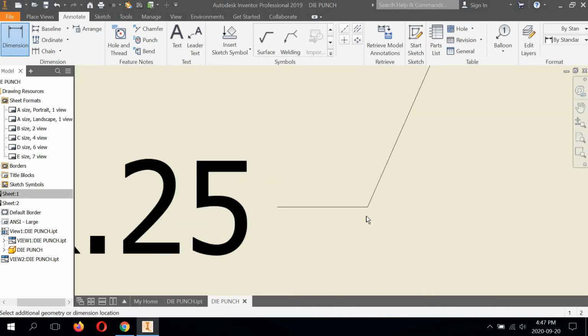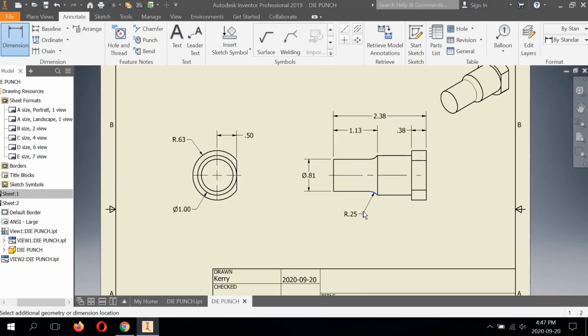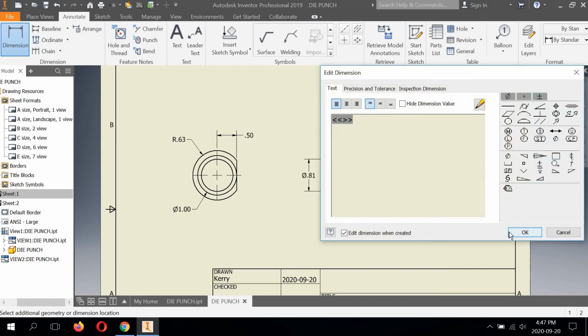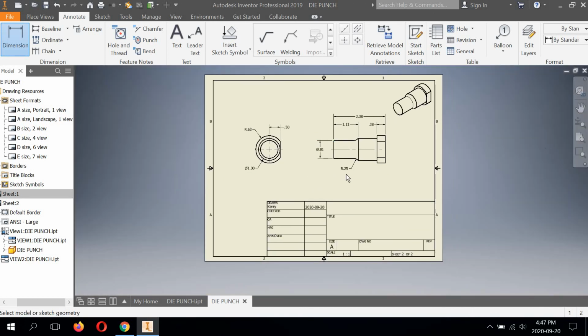Radius dimensions don't really go broken like the linear dimensions. So these ones you kind of have to eyeball to look as best you can, but I would try to copy the kind of distance we've done so far. Not too close, not too far, somewhere around there, and then hit OK. So there you have it. So there we have all our dimensions.